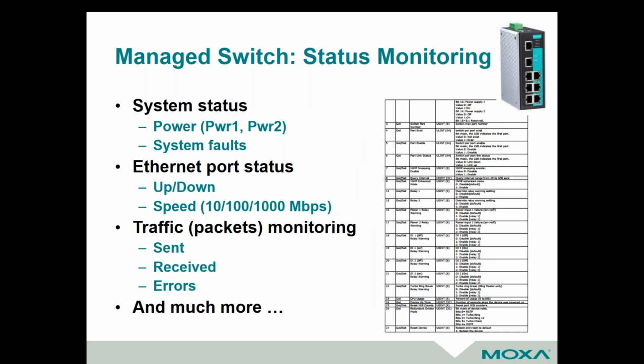So if you were to take, for example, a managed switch, remember managed switches have a secondary processor inside, and they're able to actually do a lot of things to monitor what's happening on your network and control network traffic. If any of you are using Ethernet IP on a network, you know how important IGMP query and snooping is for performance. One of the least understood things is all of the data that can be collected by those switches and how you can get it. Here's an example of a lot of objects that are a standard, and we call this a MIB, or management information base, part of the database of information that's out there that you can pull.